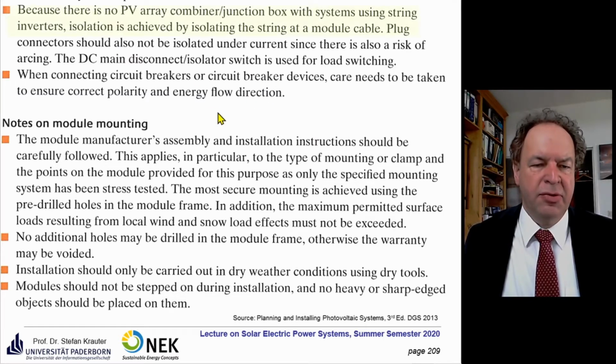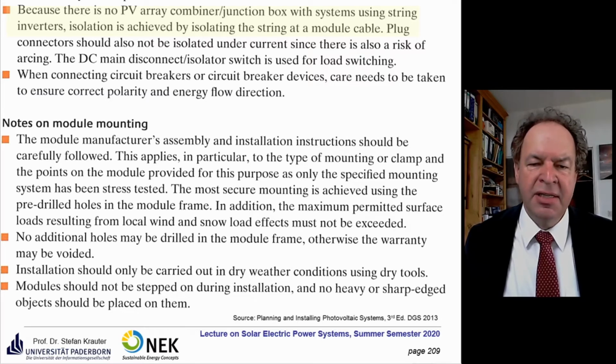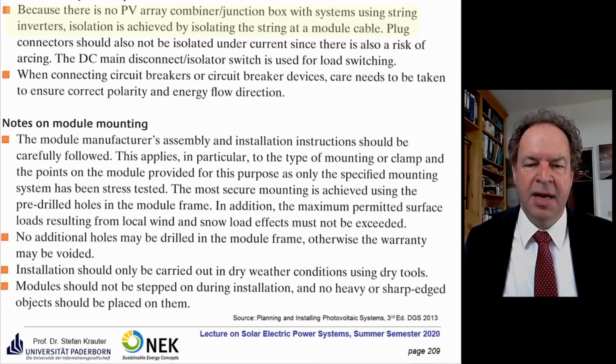This is also to be considered when connecting circuit breakers or circuit breaker devices. Care needs to be taken to ensure the correct polarity and the energy flow direction. As I mentioned already, nowadays the plugs are fail-safe, but not the circuit breakers and the other installation. You have to really check this beforehand.